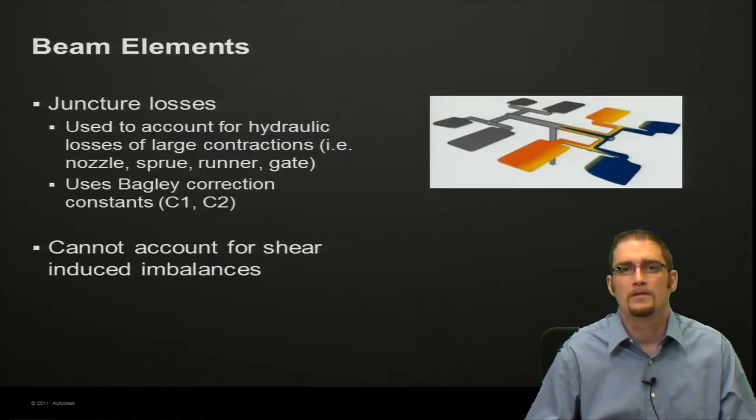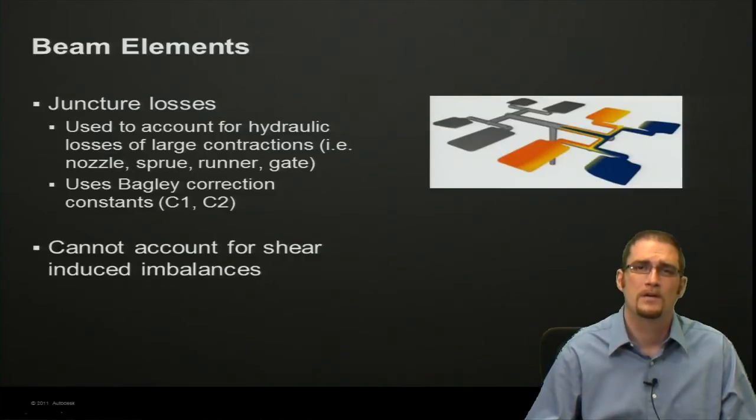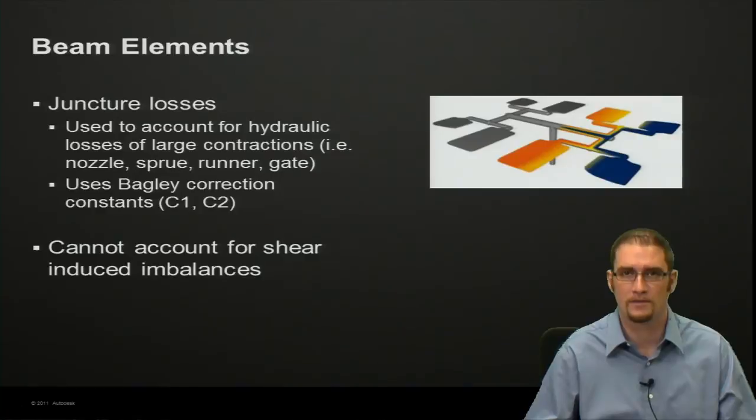The one limitation that we should be aware of is that beam elements cannot account for shear-induced imbalances. That's something that we can do, but you would want to model your feed system in, say, tetrahedral elements or a 3D mesh if this is something you're particularly interested in.